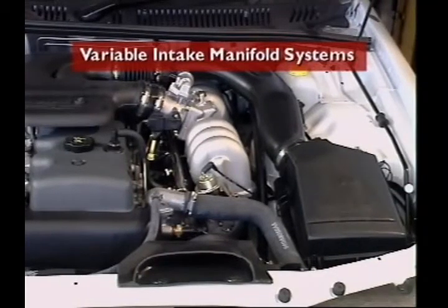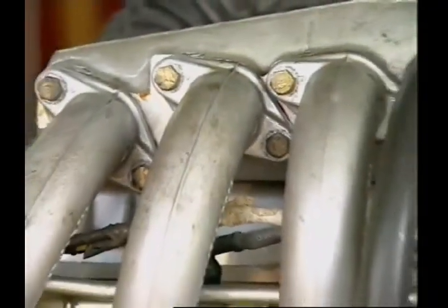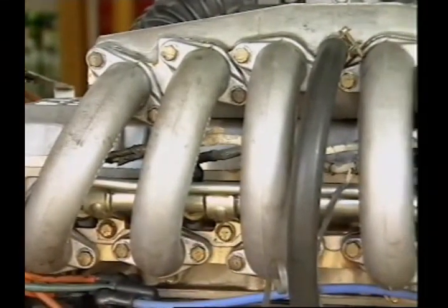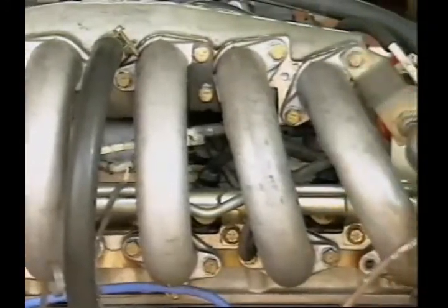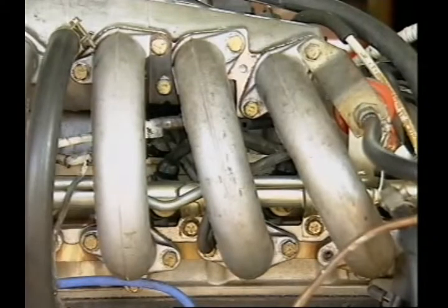This section examines variable intake manifold systems. The air intake manifold for an EFI multi-point engine normally has long branches of equal length. The long branches increase the pulsing effect of the airflow in each pipe and help charge the cylinders.